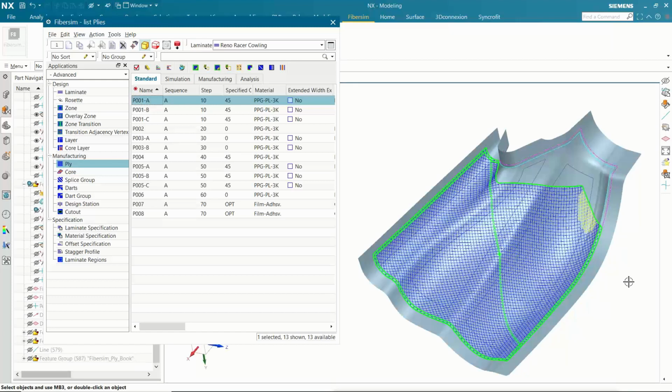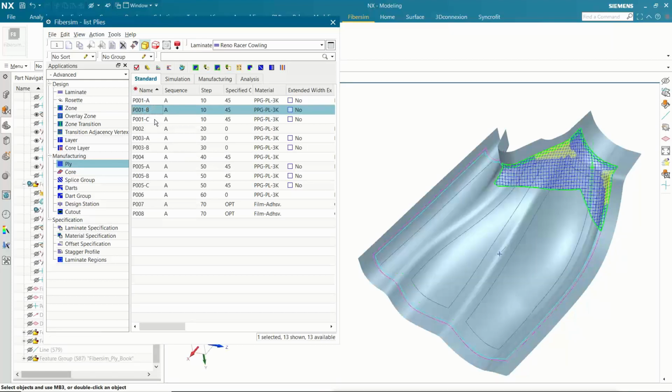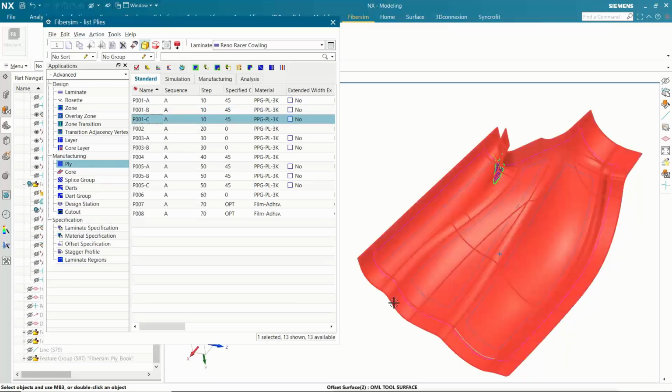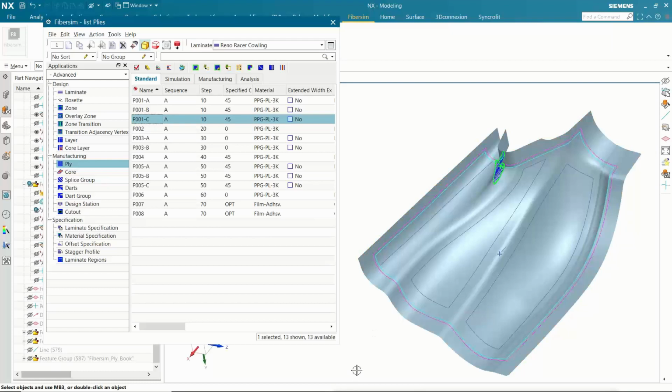If we were to see red, that means we've exceeded the limit or lock angle of the material. In this case, the material has an included angle on those little diamonds of greater than 30 degrees. And so that indicates that they have to do something to trim the ply down, to change the shape of the ply, add a dart, or splice it. So for this particular design, these 3 plies that you see here are going to be shown a little bit later being manufactured, laid up on the tool, and they laid up without difficulty.